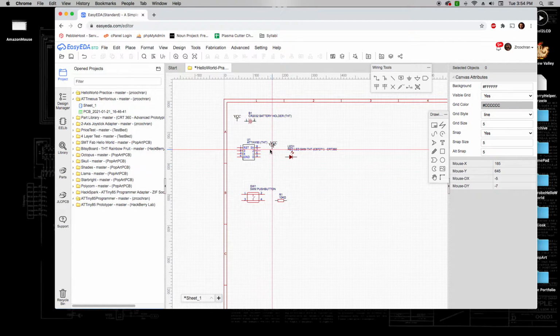Okay, so I'm going to eventually be connecting them together. For our LED, that's actually going to be powered off of one of the digital pins on the Arduino, so I don't need to add a VCC flag for it just now. On our push button, it does need a VCC, so I'm going to drop it over near pin 1.